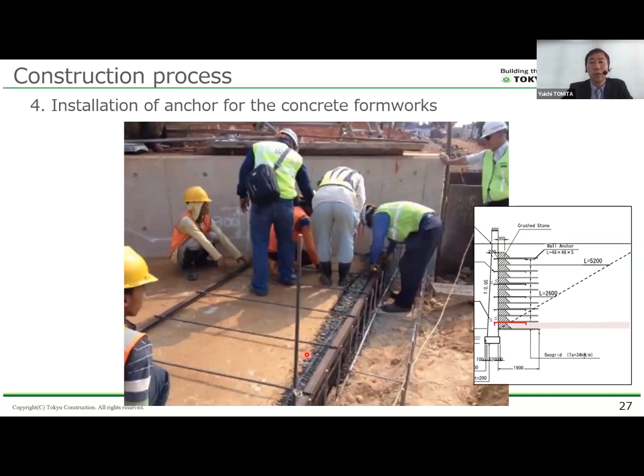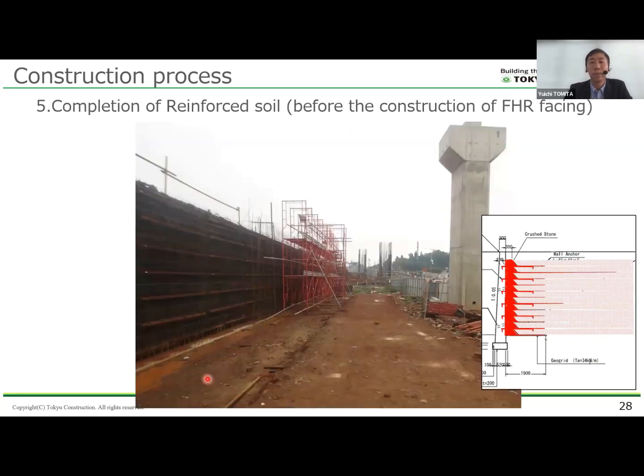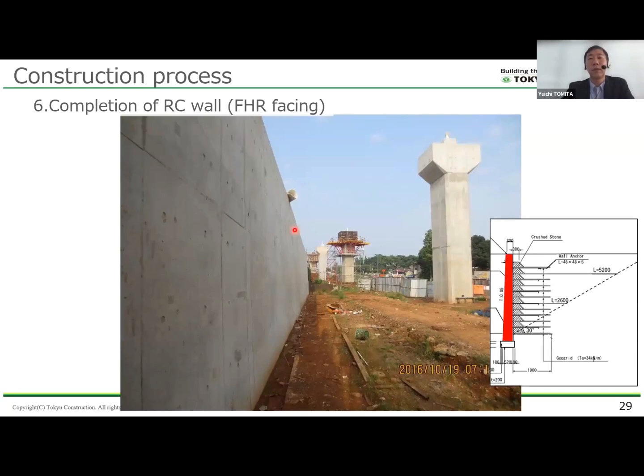Because the concrete facing uses no rear formwork, steel anchors made from a lever welded to an equal angled steel plate are installed inside the backfill. The angle steel is fully embedded to avoid damaging the geotextile above and to ensure no steel protrudes from the fill surface. The steps described earlier are repeated until the reinforced soil embankment reaches its planned height. Once completed, settlement at the top surface is measured to confirm that no further residual deformation or defects remain. Finally, the reinforced concrete full-height rigid facing is constructed by casting the concrete in place at the wall front, completing the 3RGRS structure.